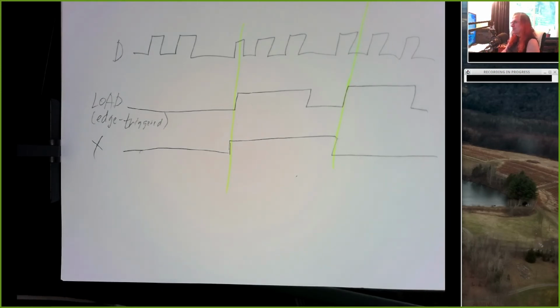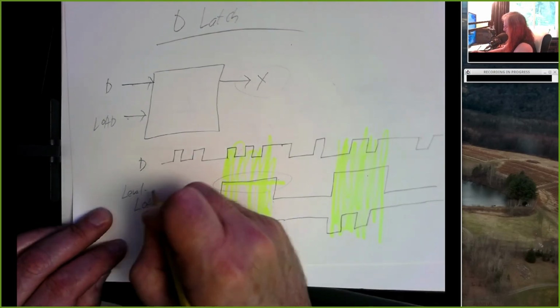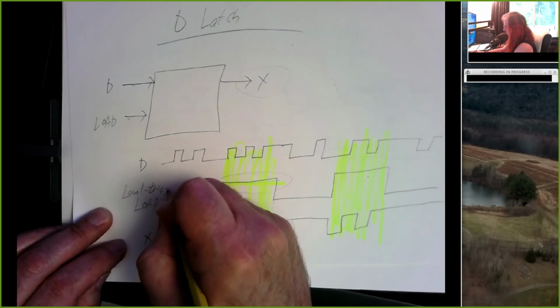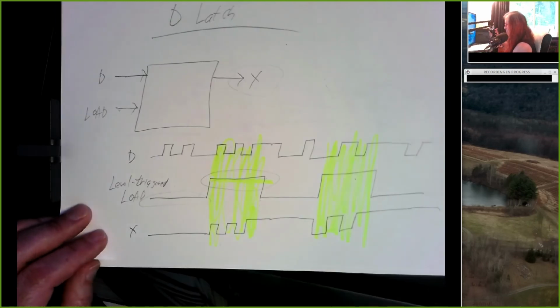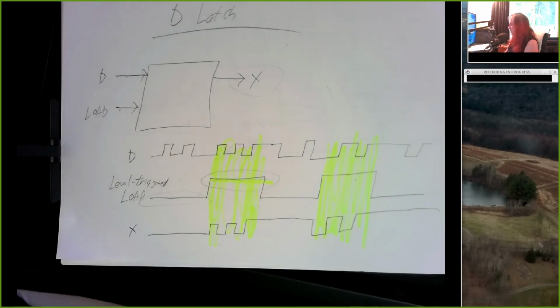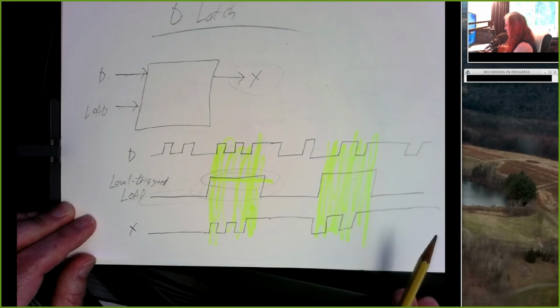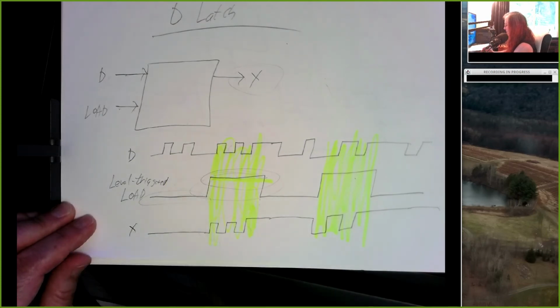All right, fundamentally different behavior. So this is level triggered. And terminology might be our latch is open, or our gate is open, as long as this is high. And while it's open, the output just matches the input.